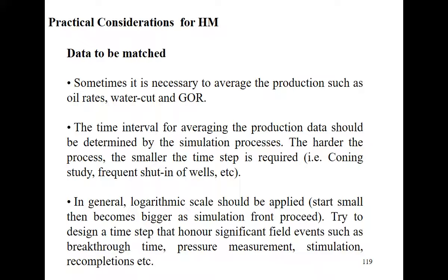Start small, then become bigger as the simulation front proceeds. Try to design the time steps to honor significant field events such as breakthrough, pressure measurement, stimulation, and opening. This is just how we adjust the time steps in order to get a match.